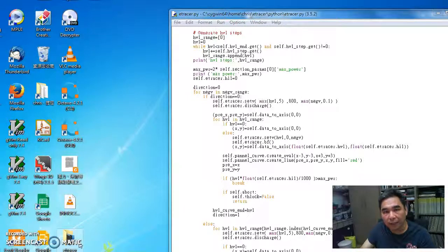Here we are dealing with a mini amp or even a fractional mini amp. So it's quite challenging, and the noise is really an issue. Fortunately, the theory of stochastic communication tells us that if the noise is white Gaussian type, we can use averaging to improve the SNR. Even if the noise is not Gaussian, the central limit theorem tells us that with enough random variables, the noise will be Gaussian-like, so we can still apply averaging.